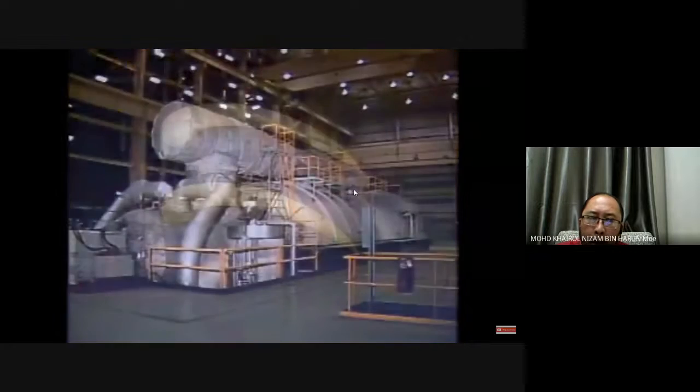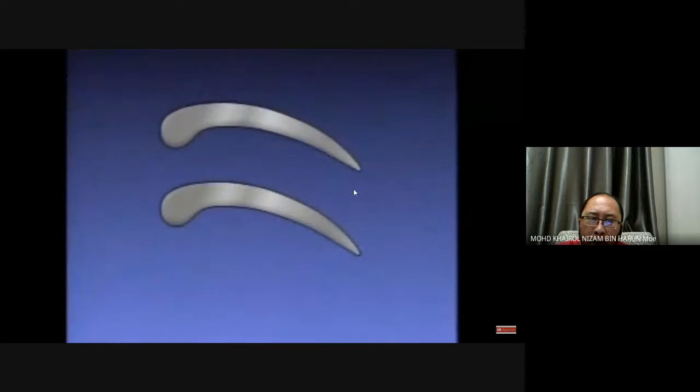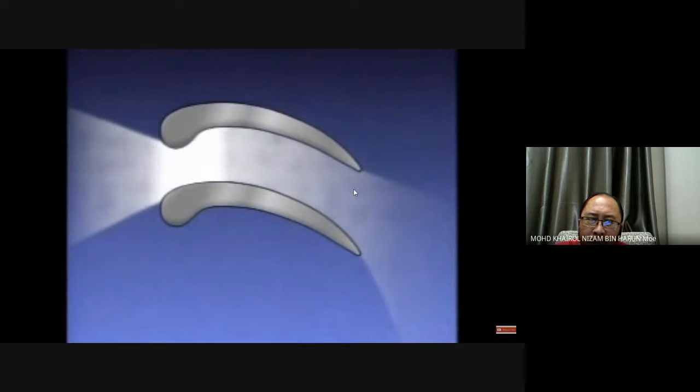In a turbine, the moving reaction blades act like the nozzle in a rocket engine. Steam leaves the blades at high speed and creates a reaction force on the blades, and that causes the wheels to turn the turbine shaft. Most modern turbines combine the use of impulse blades and reaction blades to make the best use of the energy in steam.